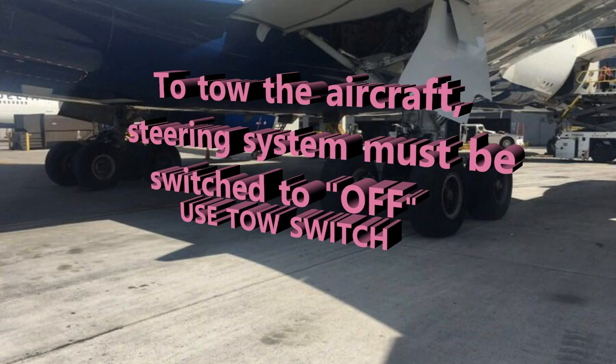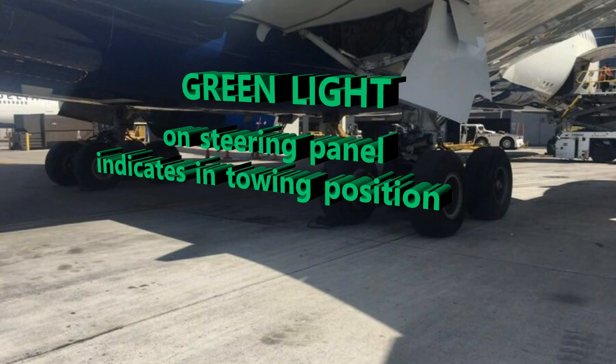So you have that disconnect panel. What it's doing is, the system is set to the towing position with a pin. The actuators are put in a bypass mode when it's in that tow position. All of the signals are sent to the CPIOMs, if you recall, your core processing input and output modules, which de-energize the isolation valve in the closed position. That prevents the operation of the steering of the wheel. There's also a green light indication right on the steering disconnect panel that shows you the switch is in the towing position.